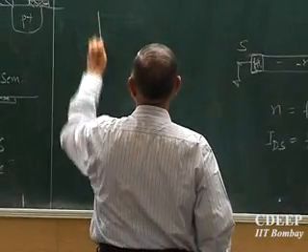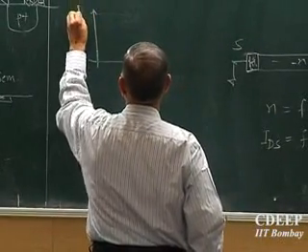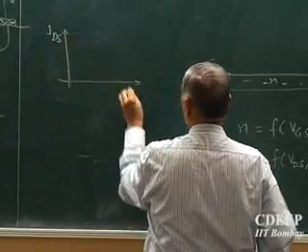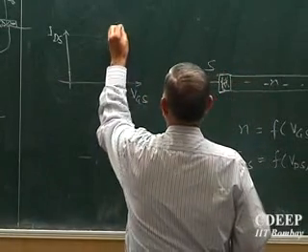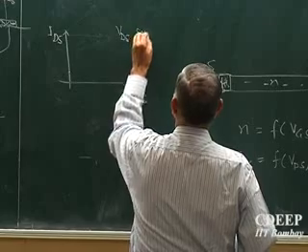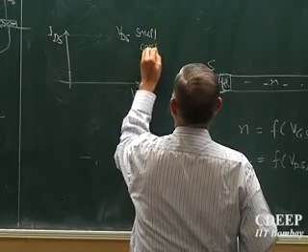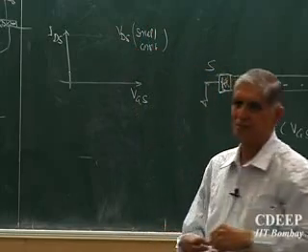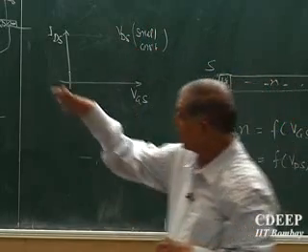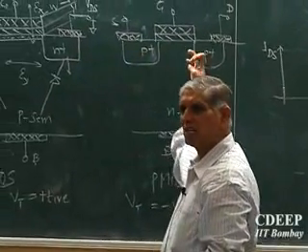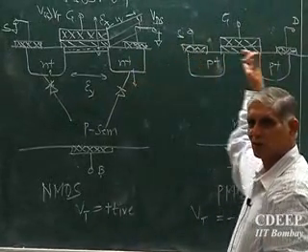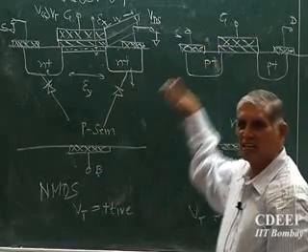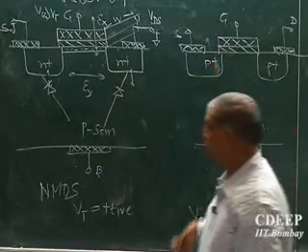We figure out, I can draw two characteristics. One, I can plot IDS versus VGS at VDS small but constant. This small word is very important. We will not do much about this. Whatever we do here, opposite polarity goes for here. There VGS is positive, here VGS will be negative, here power supply will be positive, here power supply will be negative. Everything which is valid here, opposite polarity is valid here.